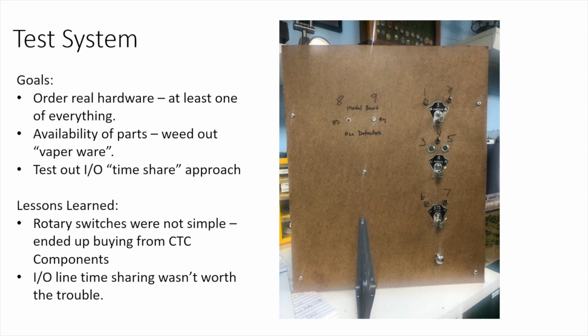Also, Ken had an idea that he had read, where he felt maybe we could cut down the number of LCC I/O boards, input-output boards, by time sharing some of the inputs and some of the outputs. So we built this little test jig there, and wired it up and drove some LEDs and panels. We definitely learned some things. Two things in particular. One is that the I/O time sharing approach turned out to be more complicated than it was worth.